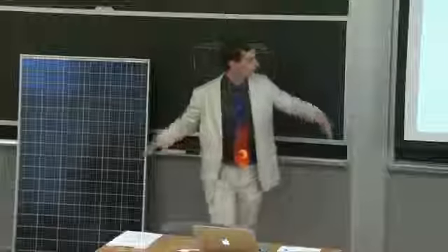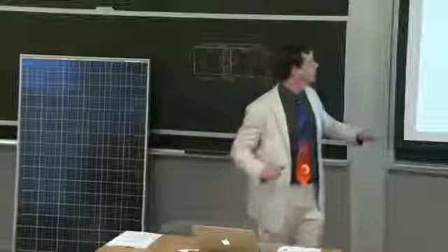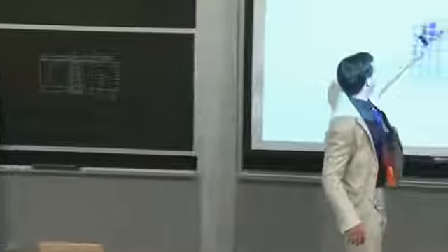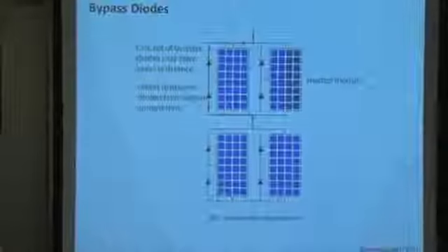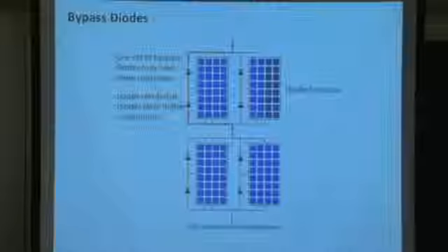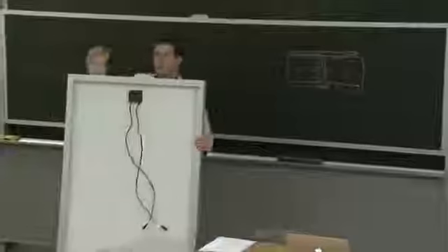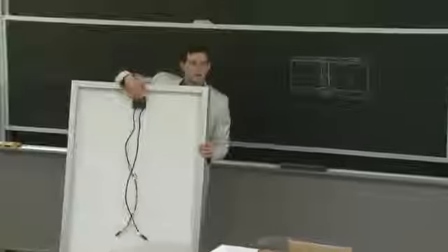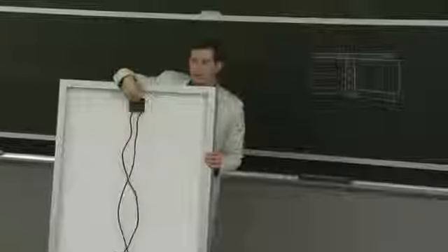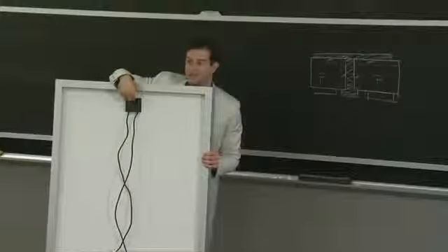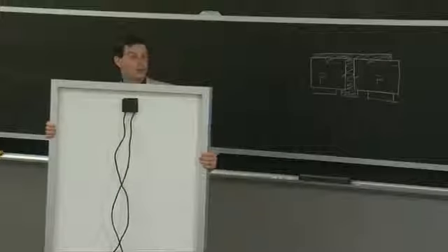So if you have a series of these modules up on the roof, you can cause the current to circumvent one of the modules that's underperforming, again, using the bypass diodes. And those are fairly standard in most of the junction boxes. So inside of here, there is some very simple electronics to prevent the modules from becoming power sinks and perhaps even drawing power from the grid.